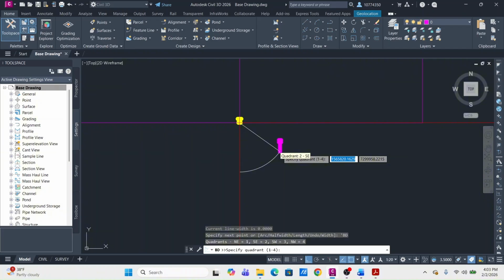For the most part, the legal description is required to have 3 parts, which is the arc length, delta, and radius. They don't have to give you the chord bearing and the chord distance, even though it would be super nice if they did, but they're not required to. But when they do include it, it makes life so much easier. But anyway, we are lucky and fortunate enough that we have the chord bearing and distance, so we don't have to do a bunch of other work to get this curve.